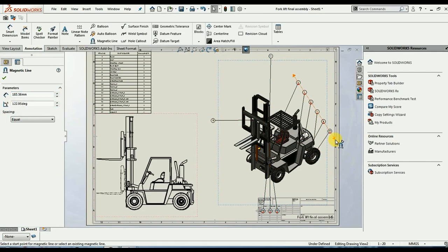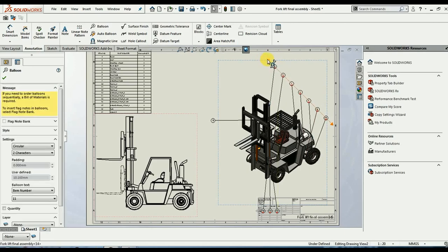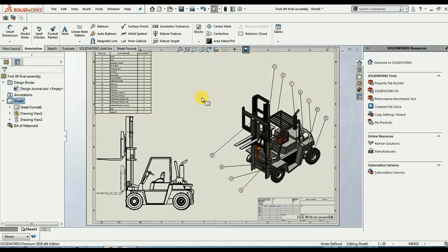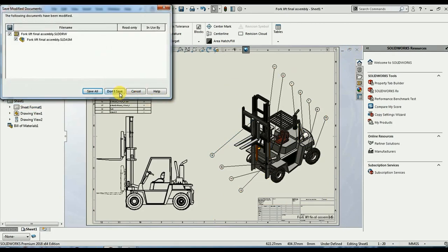See how quickly I am making the part design and the 2D drawings of the single part, and brought that model into an assembly and assembled it with the automatic relations suggested by SolidWorks, and the bill of materials for the whole assembly setup and the automatic balloons. In a similar way, the title block can also be filled automatically through the materials I apply for each individual part.